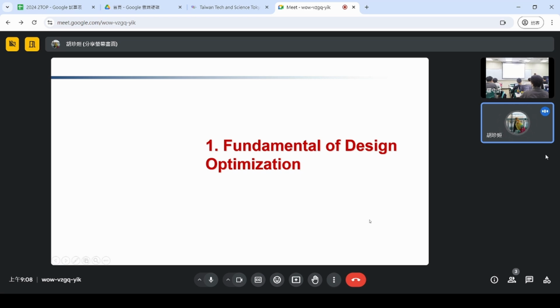After a quick observation, I noticed there is a round dimension here. Why does the engineer choose this corner to be round, not a straight corner? Because when the structure is carrying load, a round shape tends to distribute the force. So the structure can share the loading. If it's a straight corner, usually the force concentrates at the corner, so the corner can break easily.